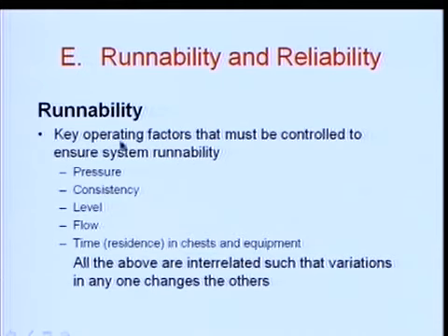Runnability, again, is the hydraulic synergism or hydraulic synergy between each module, and the key operating factors that must be controlled to ensure system runnability are pressure, consistency, level, flow, and time in chest and equipment. Without these things under control, you will not be able to get hydraulic synergy or steady state between the modules. All the above are interrelated such that variation in any one changes the other.